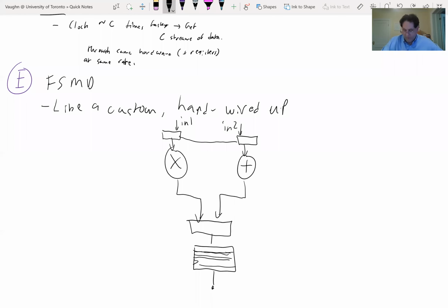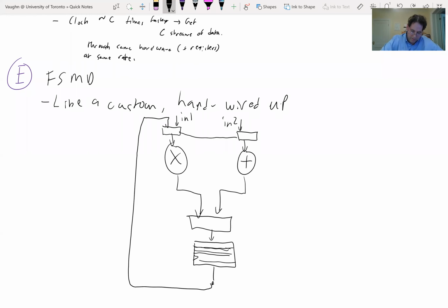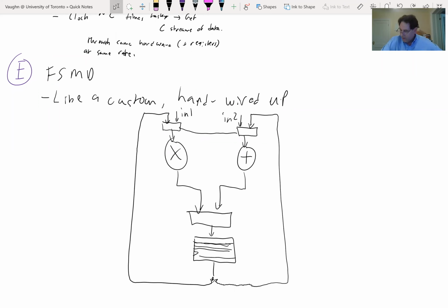Okay, so far I can do multiplication, I can do addition, I can choose where to write, I can store the result in some temporary registers. To build up more complicated computations, I want to be able to feed the output, so my temporary results, back in to my adder or multiplier. Okay, so I'm going to add some wiring to do that.